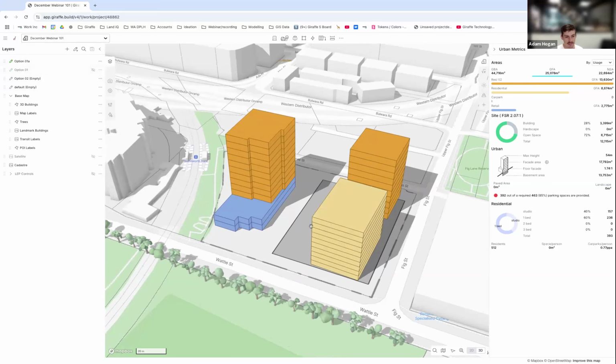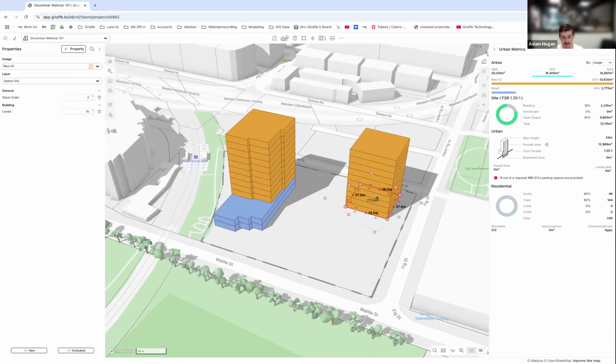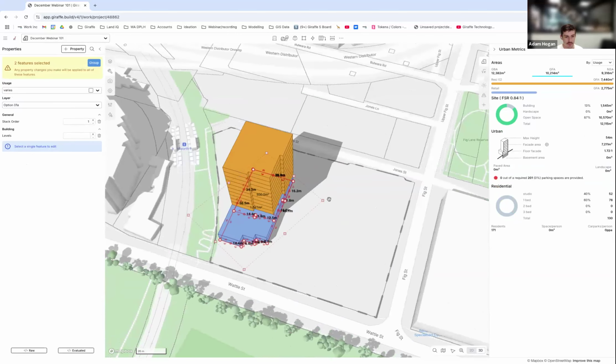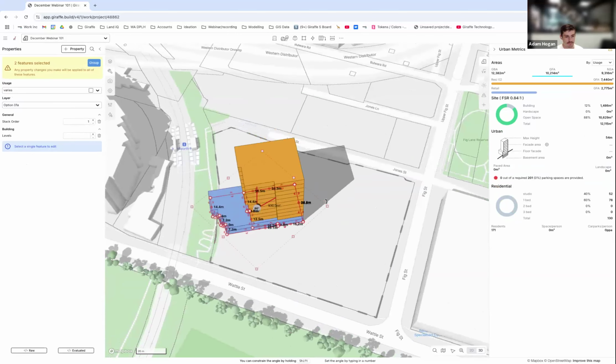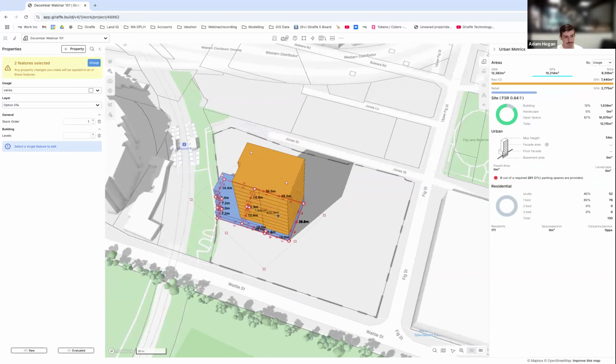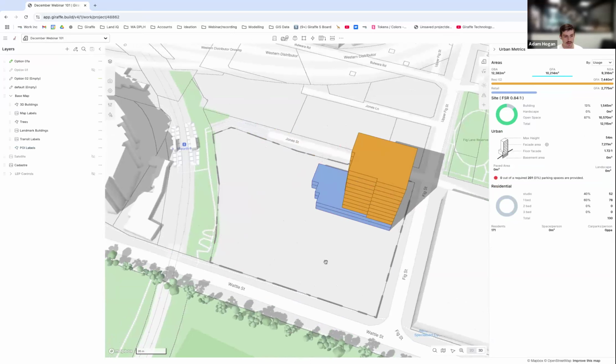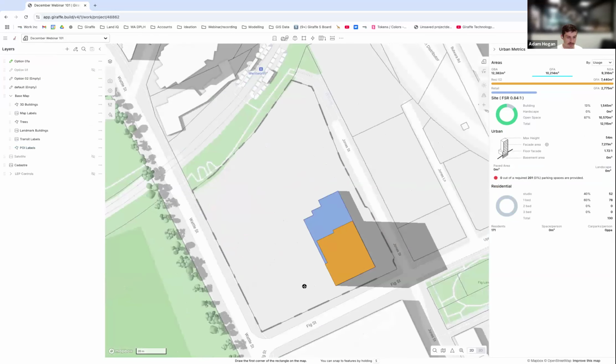And I wanted to test maybe no car park, delete those towers, and maybe we rotate this 90 degrees and reposition it over here. I'm hitting R on my keyboard, toggling into 2D mode with T, and then I want to draw a landscape element.